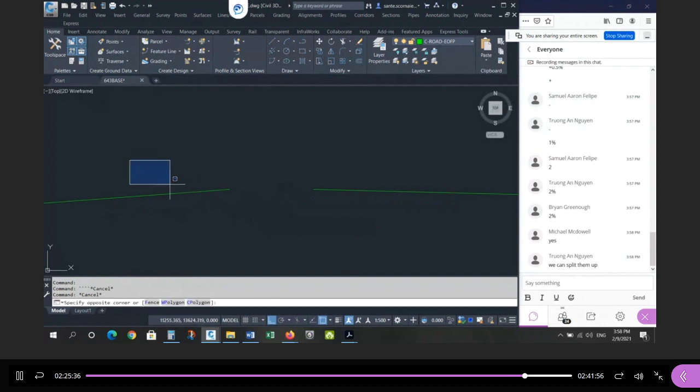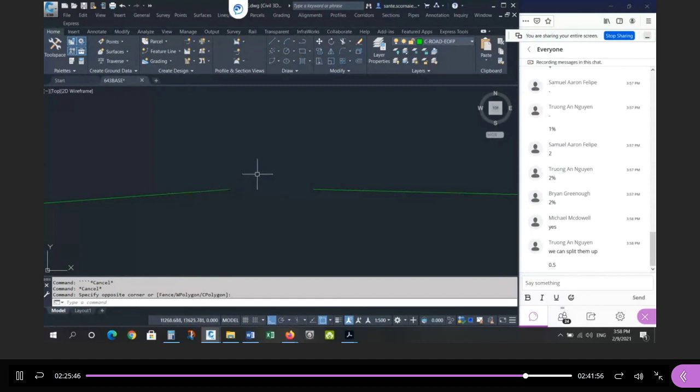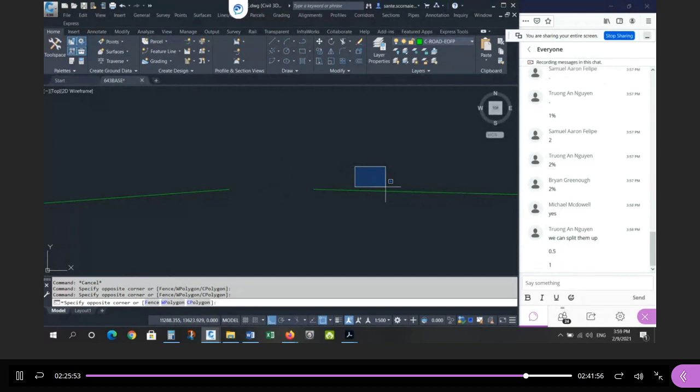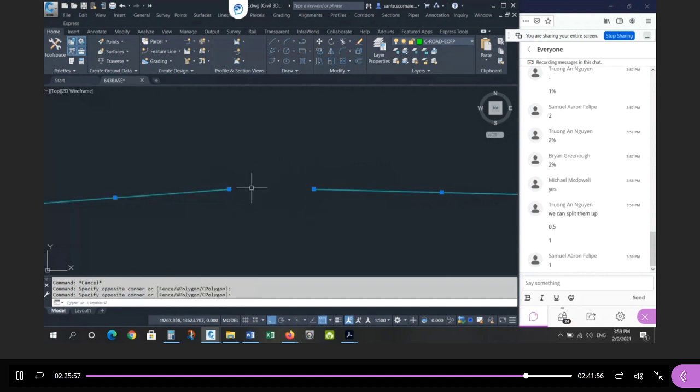I want to go from positive 1.5. What's 1.5 subtract 1? 0.5. What's positive 0.5 subtract negative 0.5? So if I put in between here and here something that's minimum length, 10 meters, with a positive 0.5% slope, then I'll have not one but two PVIs where each one has a grade change of 1%.